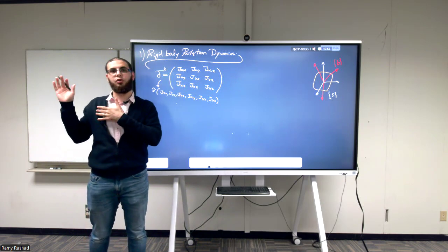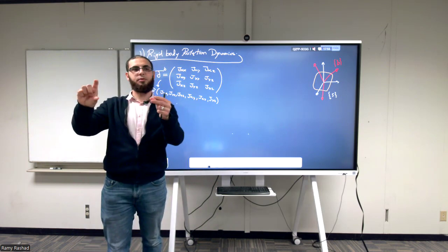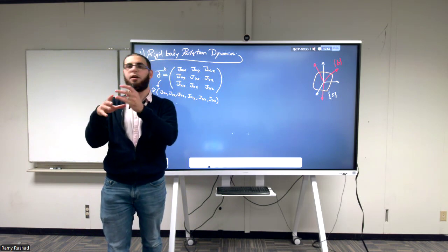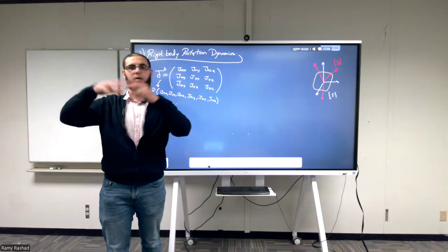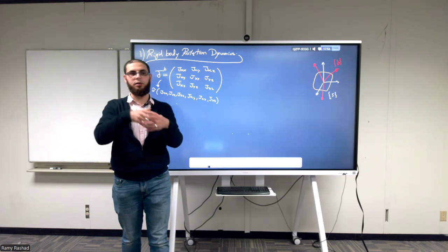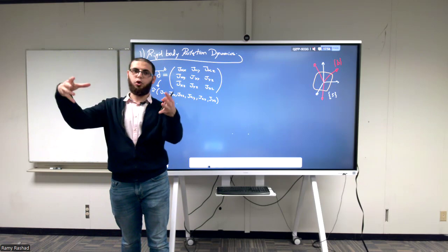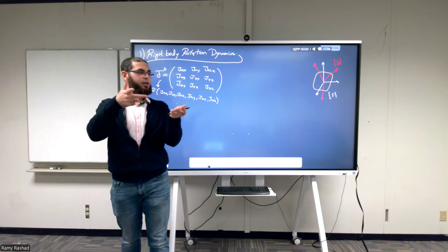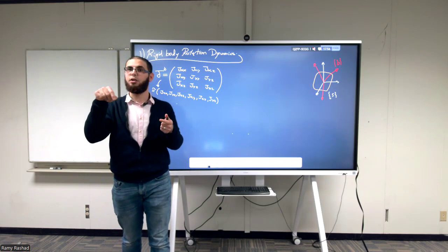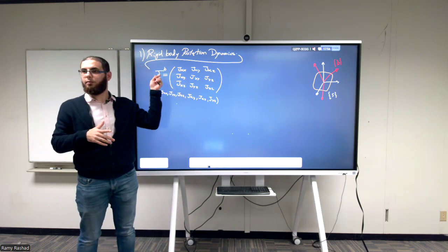How do we do it in practice? How did you learn about it in undergraduate studies? You take elementary objects, for example a sphere, and you have some formulas for calculating depending on the density. You take, for example, a cuboid or a triangle or a prism and so on. These are just basic shapes. In practice, how do we do it? You go to SolidWorks or your favorite CAD program. You draw your object and you tell it, okay, I want the moment of inertia in this frame. You have to specify what frame you're talking about in SolidWorks before it gives you the numbers. You have to tell it which frame you're talking about.